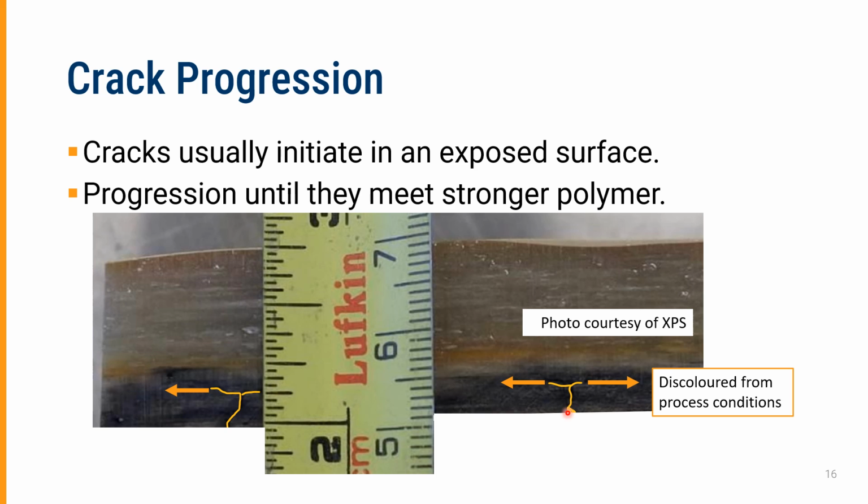And these cracks form, but what happens is, as the crack penetrates into the material, it does not propagate the same way that it would in a metal alloy. In a metal alloy, we'll often see the crack propagate normal to the stress direction. But here, we get to the point where this crack comes to material that is stronger and resists the crack propagation.